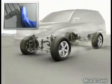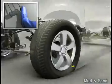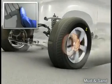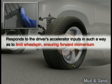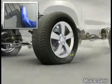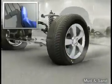The natural tendency for a driver when traversing a sandy embankment would be to accelerate when sensing the vehicle beginning to bog down in the sand. In the mud and sand mode, the Multi-Terrain Select system automatically responds to the driver's accelerator inputs in such a way as to help limit wheel spin and ensure forward momentum. In this case, by limiting engine torque and engaging A-Track to allow more wheel slip than normal.